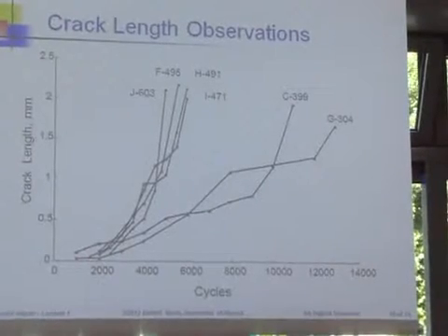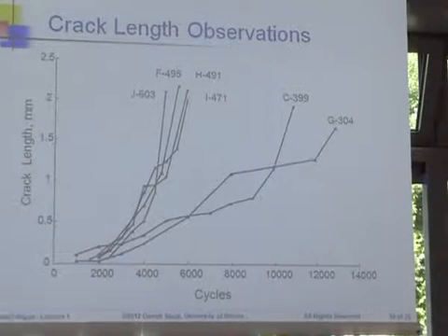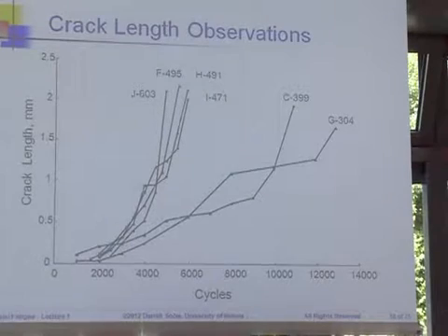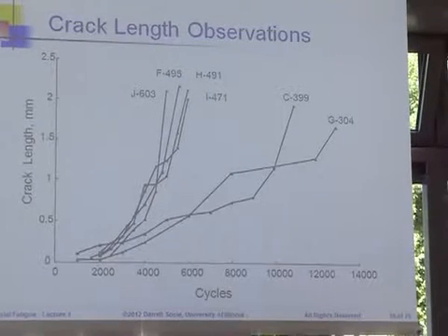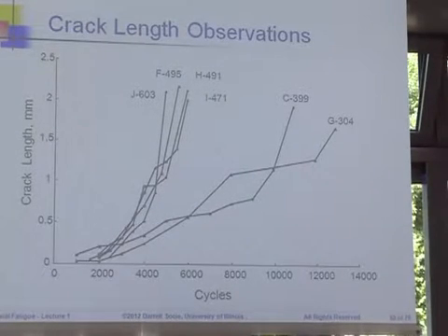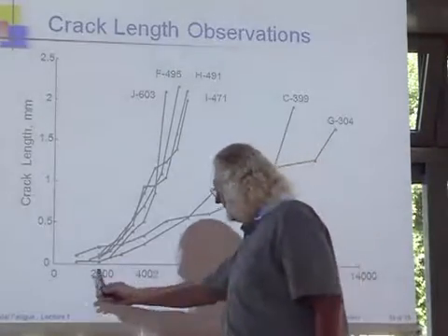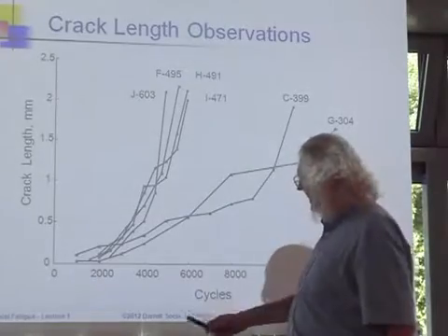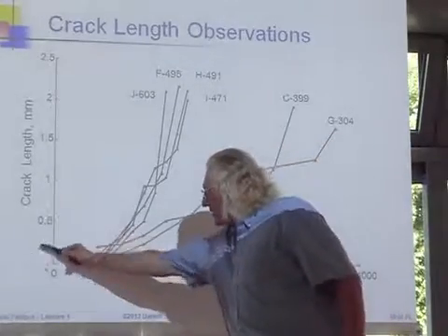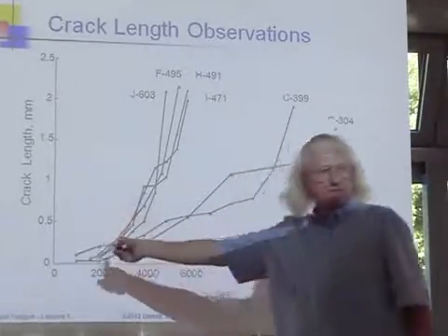By the way, if you look at what happens, the numbers on the top of these, the letters represent different loading paths. We'll revisit this slide a little bit later. The top numbers are stresses. And what you see is that if you think about it, you look at the lifetime along this axis, almost all of the lifetime is taken up, and these cracks are very, very small.